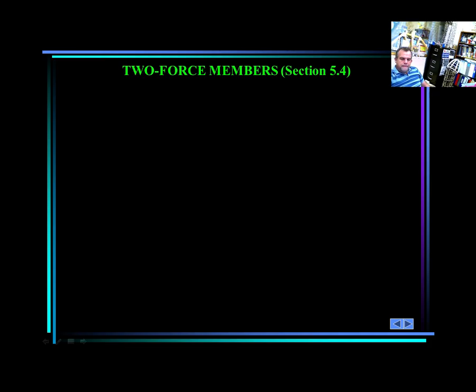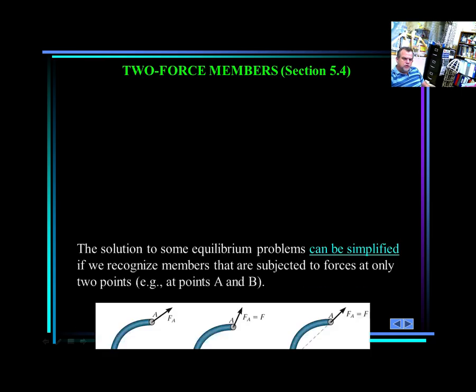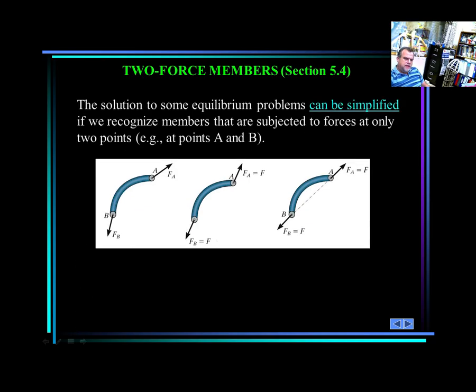Okay. Another thing that was covered is a two-force member, and this is just a really quick basic definition. A two-force member is, whenever you have a member like that, if you neglect the self-weight of the member, it is not taken into account, is negligible. The only possibility, if you have a force here in this direction acting, for this body to be in equilibrium is that the other force has to be acting in the same line. And this is called a two-force member.